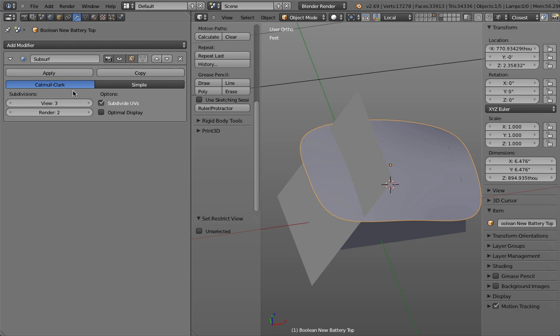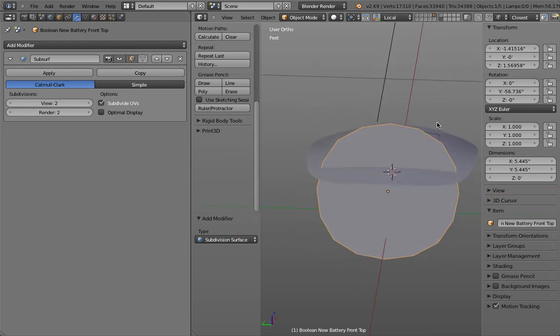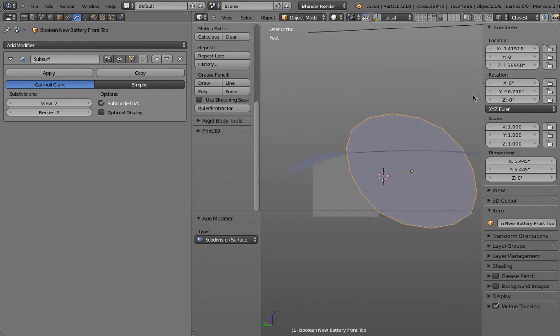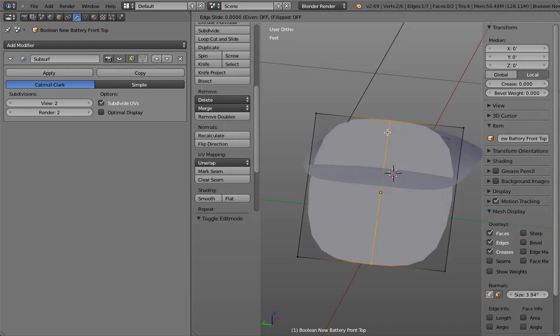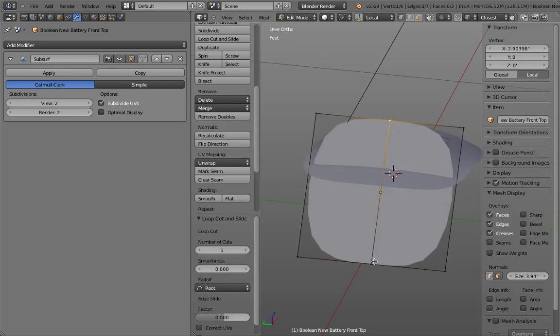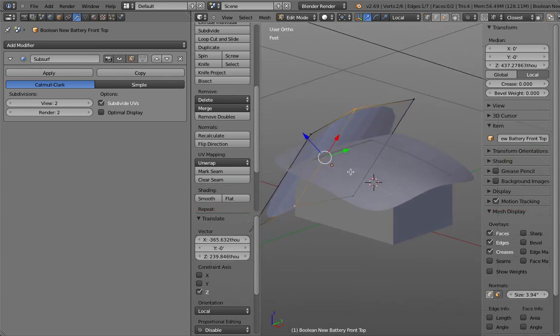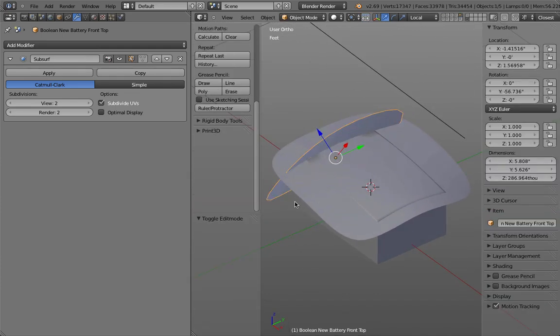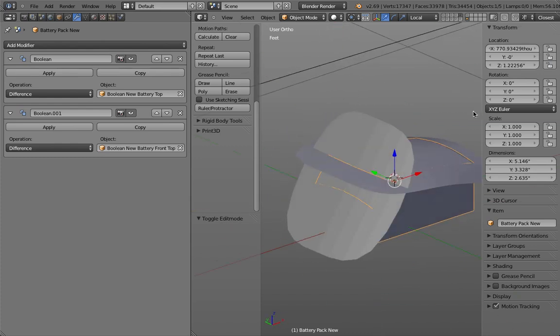And when you really want to quickly play through some ideas, this is actually a much faster and productive approach. So for example, right now I could add a subsurface modifier. Just make sure it really penetrates my form model. Go into edit mode, add a loop cut, select those 2 points, and maybe move those up a little bit. And then you see though that the form model adjusted to it.